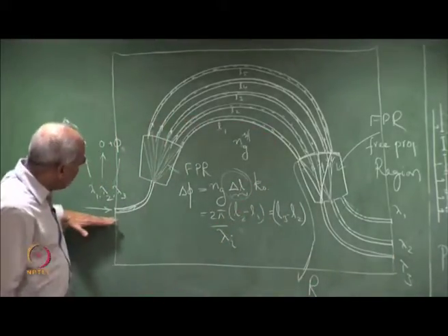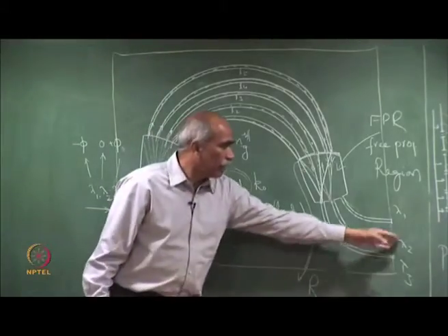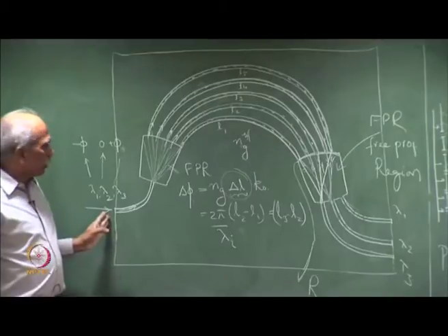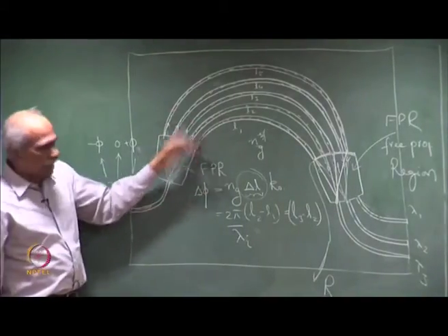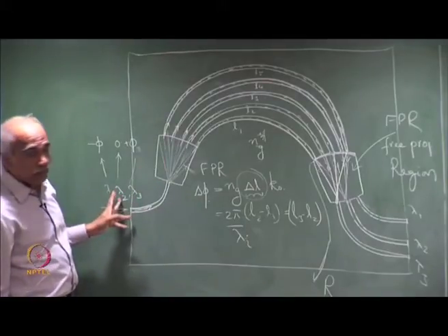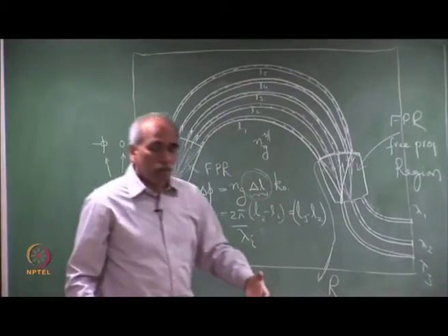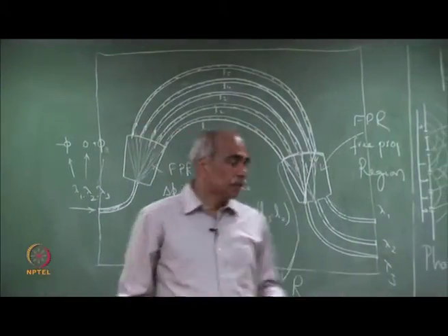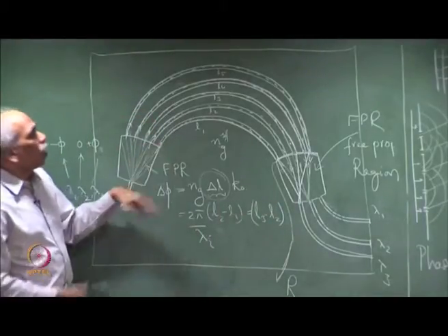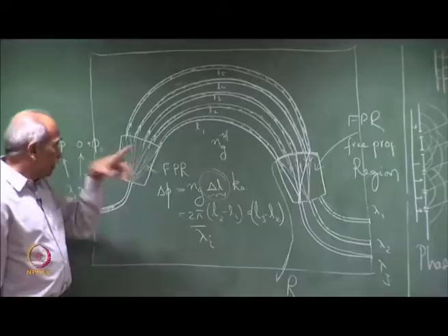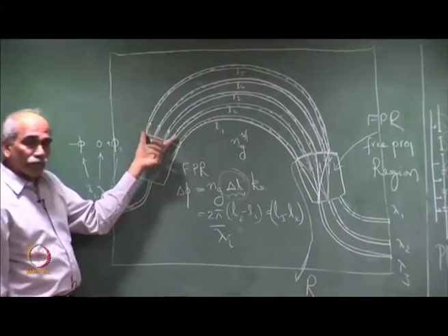Accordingly, the locations of the output waveguides are positioned. So, what we have is a multiplexed input. I have illustrated considering only 3 different wavelengths. The number of waveguides in the array has nothing to do with the number of wavelengths, but depends on the requirement of resolution and on how much loss can be tolerated. There could be different numbers of waveguides in this array.